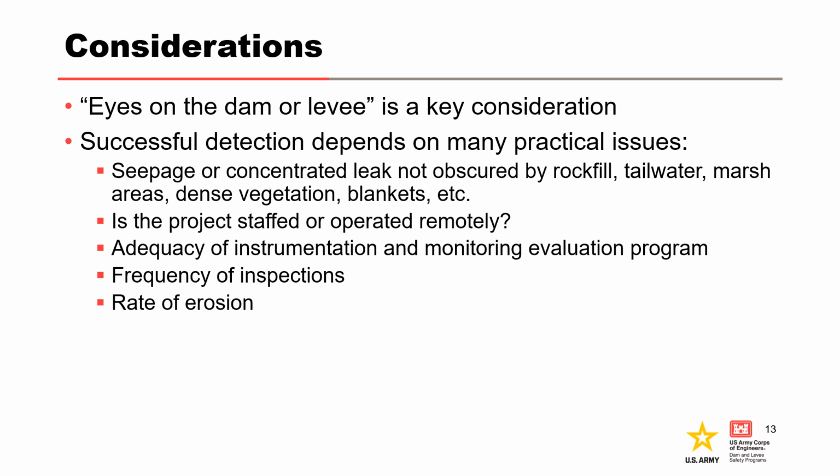Given that the evidence of internal erosion is observable, the following questions should be asked during a risk assessment. Is the project staffed or remotely operated? How often is the dam or levee observed or visited? How close does the public get? Are local officials such as police, park rangers, recreation staff, or the levee sponsor trained in dam or levee safety?